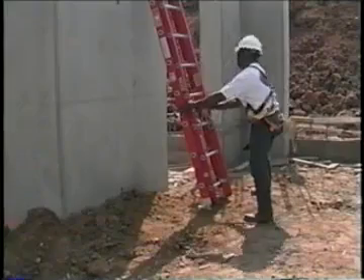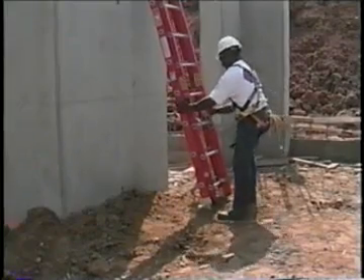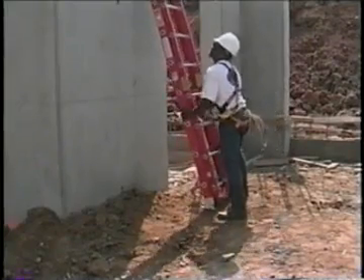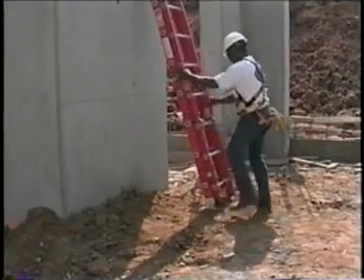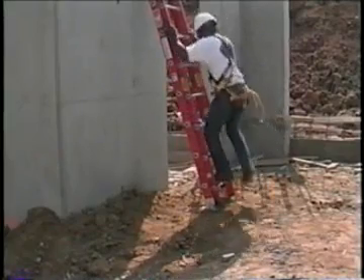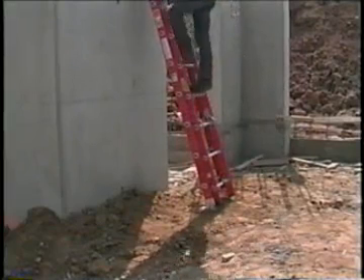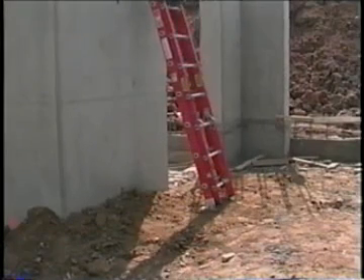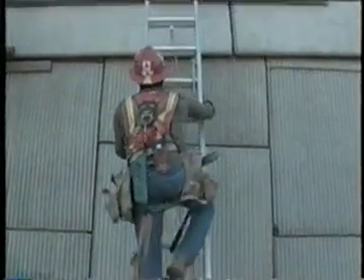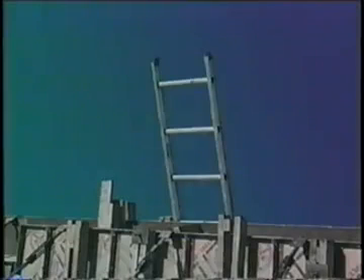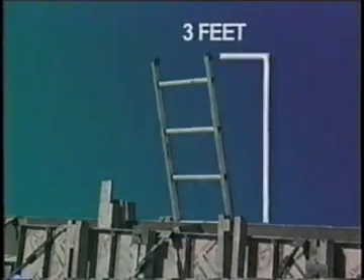To avoid having a straight ladder slip out from underneath you or from falling backwards, position the ladder so that the base of the ladder is at the most stable angle for climbing. The distance from the base to the wall should be about 1/4 the working length of the ladder. If you're using a ladder to gain access to an elevated area such as a roof or platform, check to be sure that the top of the ladder extends at least 3 feet above the roof or platform. If it does not, go get a longer ladder.